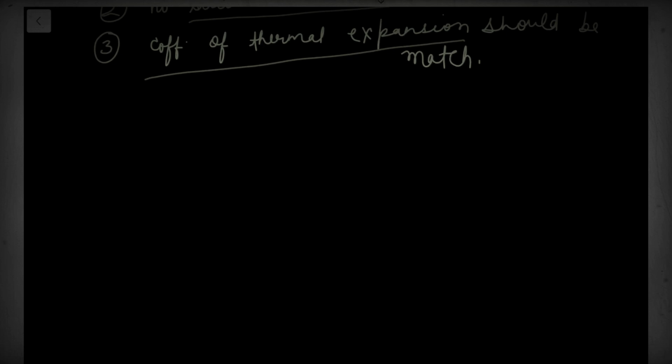Bipolar integrated circuits utilize epitaxial structure in the same way as discrete transistors utilize it. The substrate and epitaxial layer have opposite doping types to provide isolation, and a heavily doped buried layer or diffusion layer serves as a low resistance collector contact. Unipolar devices such as FET and VMOS technology use epitaxial wafers.